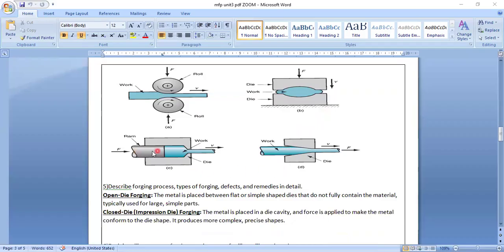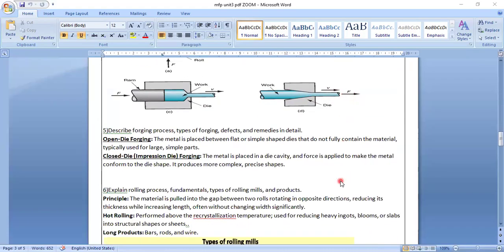Here also you can see the force is given from the backside. Here is the workpiece, and this is the ram. The ramming is done on the material, and it comes out with some velocity v. This is the workpiece. Here this diameter is changed to this diameter, so pipes are reduced to tubes or wires. Again, these tubes are forced to go through the die and come out as wires, also with some velocity vf as shown in the figure.